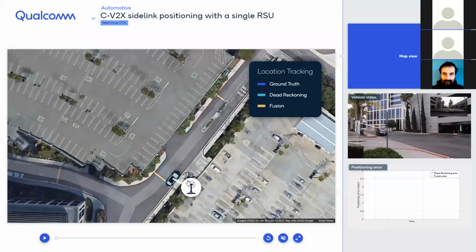Because millimeter wave or radar is more hardware. So here we are using only a typical sub-6 gigahertz frequency signal, and we show that we can still achieve good enough, within a meter of accuracy for the vehicle, which is not bad. It's not equivalent to radar, but it's not bad for sub-6. And given that the unlicensed spectrum is available at 5 to 5.9 gigahertz, that can easily give you more than 100 megahertz of signal. That's not a bad deal, basically.